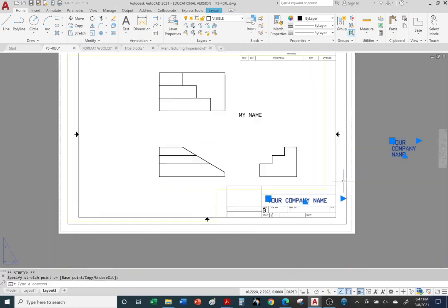All right, so if I wanted to move my name, I have to double click inside. So once again, you're looking at a picture in your phone. And now if you want to move this text, you have to be inside your picture, or model space, right? And currently we are in model space. If I want to go back to paper space and move the text on paper, go back.